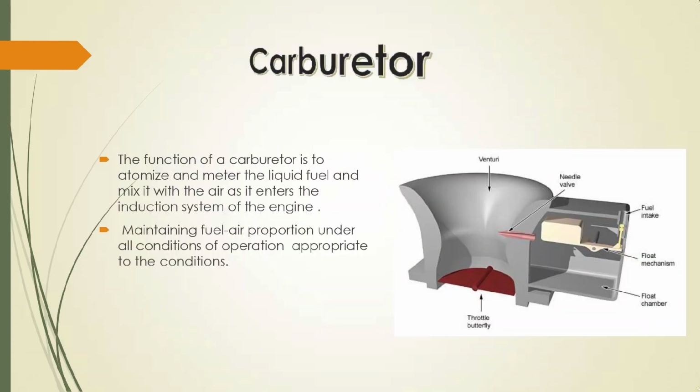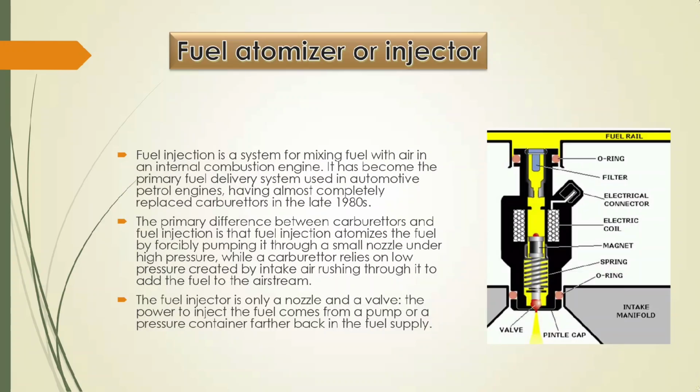Carburetor is a device which is used for mixing the fuel with the air, maintaining fuel air proportion under all conditions of operation appropriate to the conditions. Fuel atomizer or injector is used to inject the fuel into the combustion chamber. It is finally spraying the diesel into the combustion chamber.